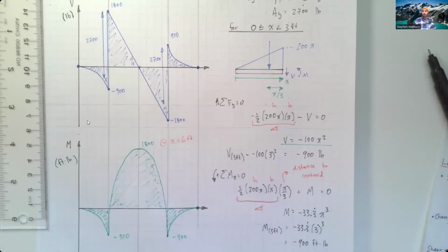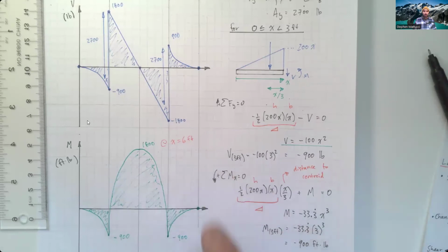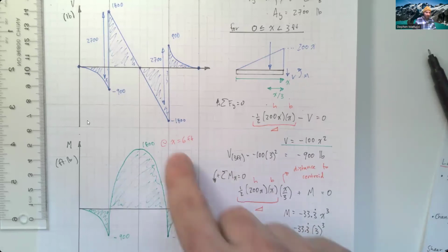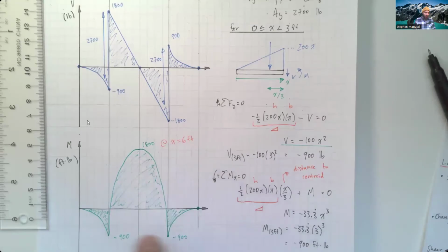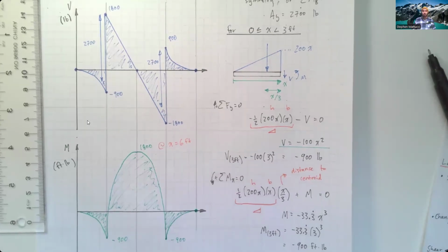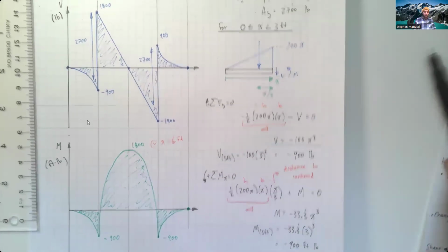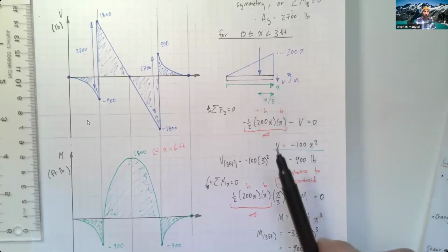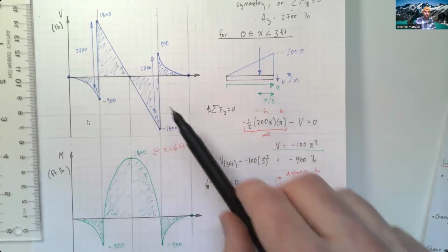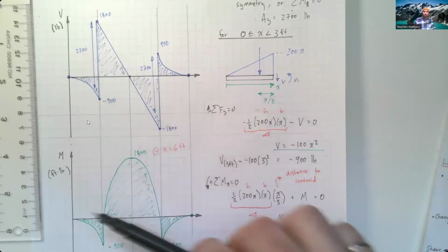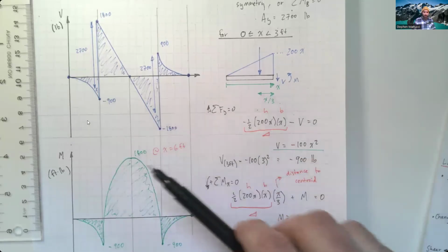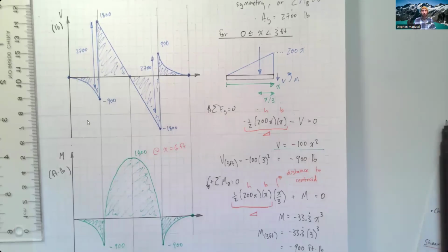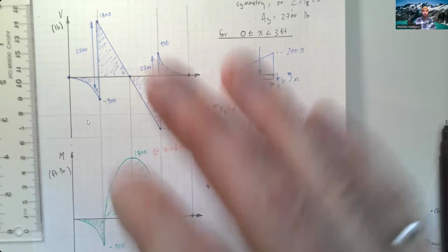So the really important thing here is to show the shapes of these curves and then identify, especially on our moment diagram, any of these peaks or valleys in these main areas here. And so, just kind of reflecting on this, you saw this one, we started off really systematically drawing our free body diagram, developing our equations such that we can start drawing our diagram. And then once we had some shapes, we kind of had an idea of what was going on. Then we went to our relationships between these different graphs.